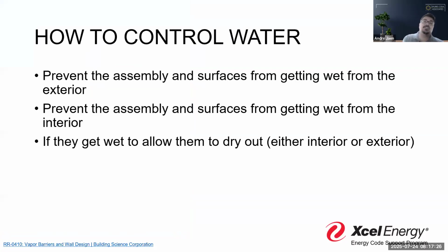Now, the ideal circumstance, right, is to prevent water from intruding in the first place, and prevent any assembly from getting wet on the interior. But we also know that there's some places that are always going to get wet in the interior, right? Think of your bathrooms. Think of your kitchens. Think of the places where you're boiling water and that vapor is getting up to the ceiling, and there's only so much you can do. You've got your mechanical ventilation, and hopefully it's the right size to be able to take that out.